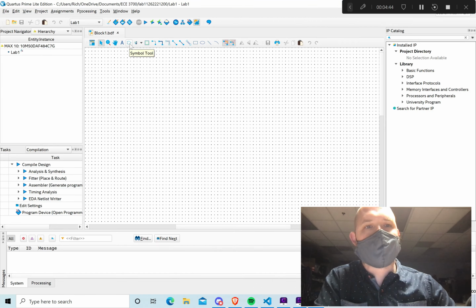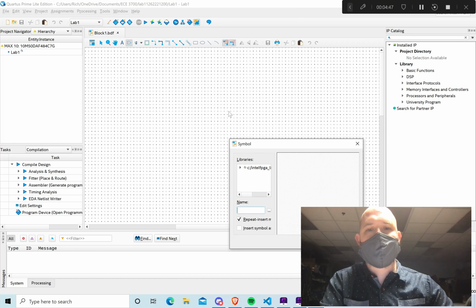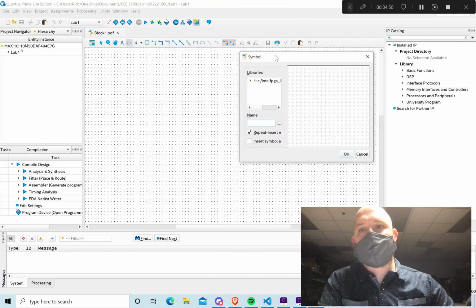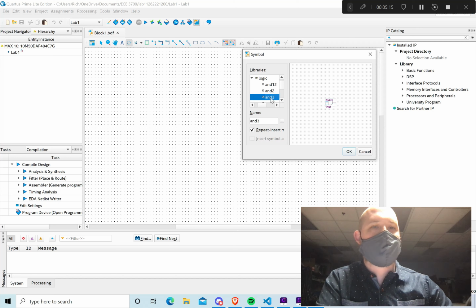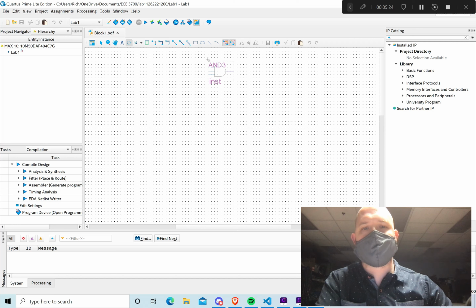So we're going to start by laying down our AND gates. These are going to be 3 input AND gates. Previously I had showed others how to use the bus syntax, and it seemed to be causing more problems than it was solving. The syntax was a little confusing, so that we can get through this lab and not cause more problems and time, we're going to do it just with wires. We're not going to worry about the bus syntax, and if you know how to use it, if you understood the previous examples I showed, great, and if not, I'll try and explain it again in a future lab. But for now, to get us through this one, let's just go with the simple wire setup.